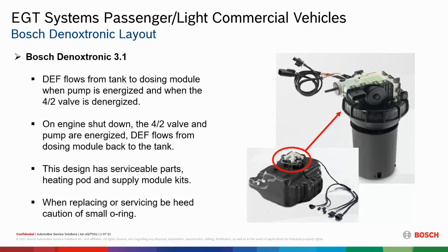And what that's going to do is take the DEF fluid and flow it from the dosing module back to the tank. Basically, we're going to purge the lines of fluid, evacuate them. This design does have serviceable parts. It has a heating pod and a supply module that can be replaced separately.